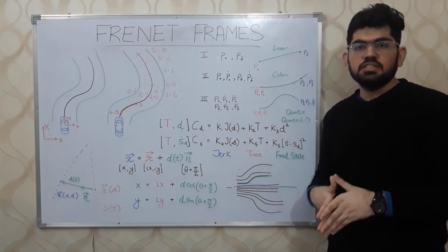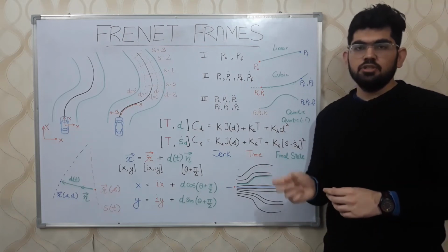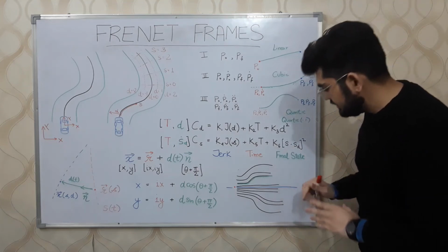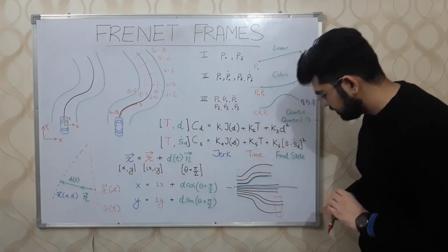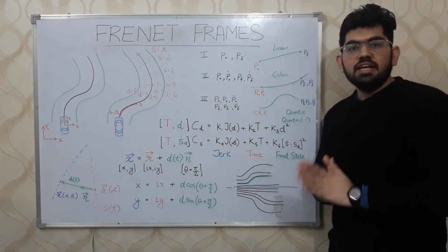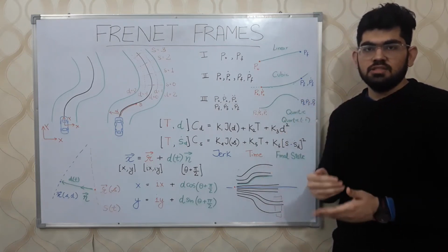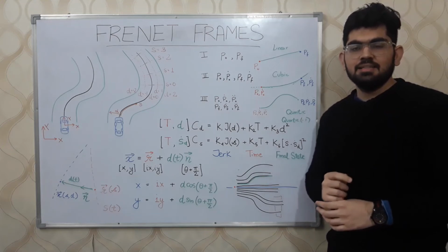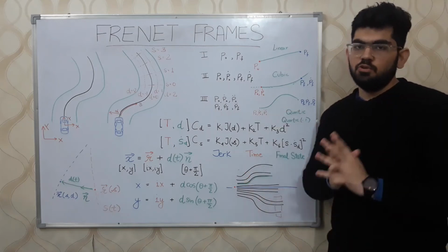Before calculating the cost function for all the different paths, the first step we do is obstacle avoidance and introduce certain other constraints. For instance, if we have an obstacle over here, something like this, then these three generated paths will be immediately discarded. We can also discard some other paths that do not follow certain constraints like crossing the velocity limit or crossing the curvature limits. Finally, from the remaining paths, we calculate the path that minimizes these cost functions and give that to the robot to follow it.